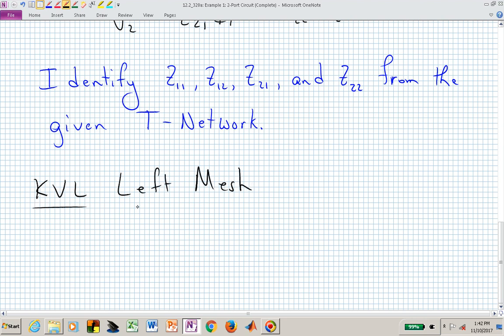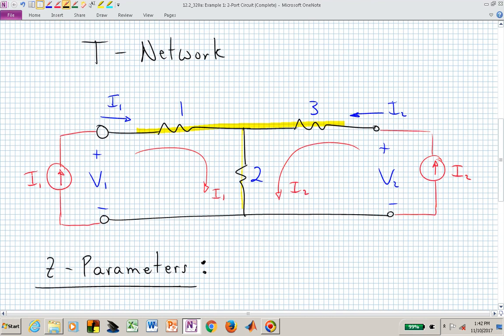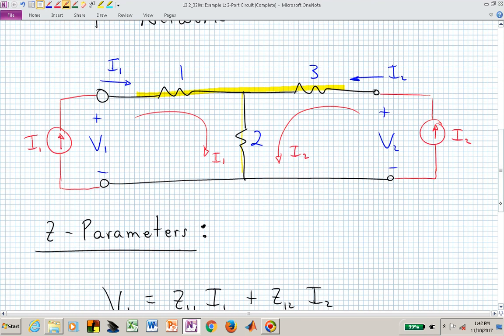And this is now after we've applied these two different current sources, and because this is a linear system, we can actually look at using superposition when it's helpful to us, meaning we can set I sub 2 to 0 and analyze the circuit. We can set I sub 1 to 0 and analyze the circuit. Let's go ahead and assume right now that both sources are energized and they're now playing into creating V1 and V sub 2 in this interconnected circuit.